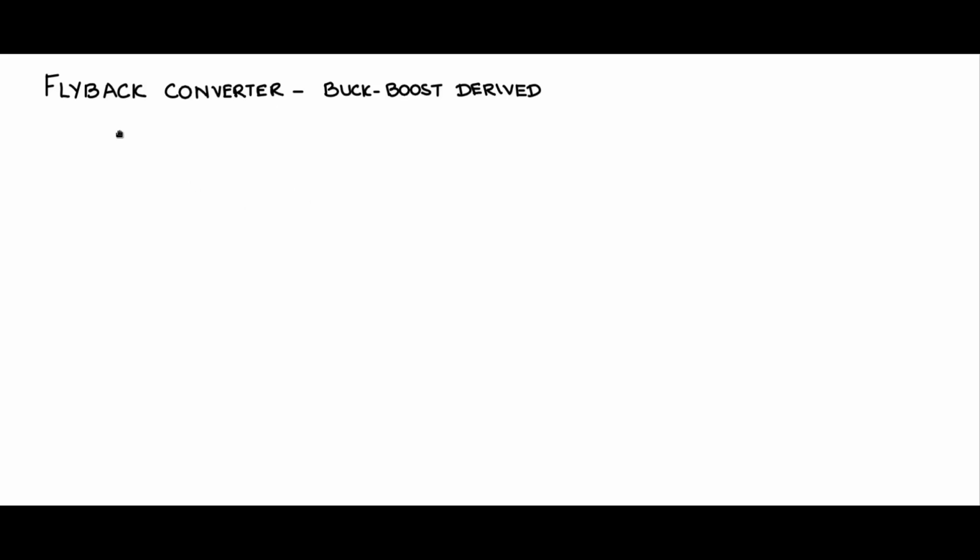Let us now discuss another converter, one of the most popular converters that you will find in most power electronic equipment, that is the flyback converter. It is a buck boost derived converter. The forward converter was a buck derived converter. The flyback converter is the buck boost derived converter. And let us see how the isolated buck boost derived converter looks like.